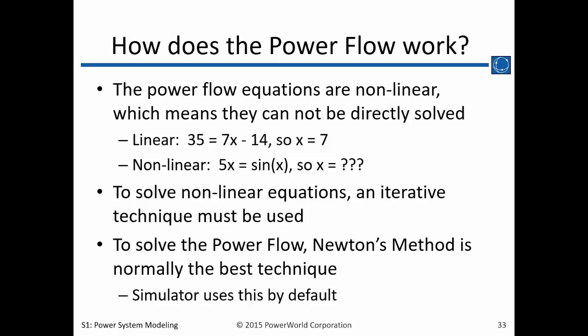But Gauss-Seidel has a really hard time narrowing in on and being accurate to the actual solution, and it also does not handle negative impedances, which you do run into quite frequently in a load flow model, in modeling three-winding transformers, and in modeling series capacitors. And so Gauss-Seidel is not an option in Simulator because it does not handle those typical modeling conditions.